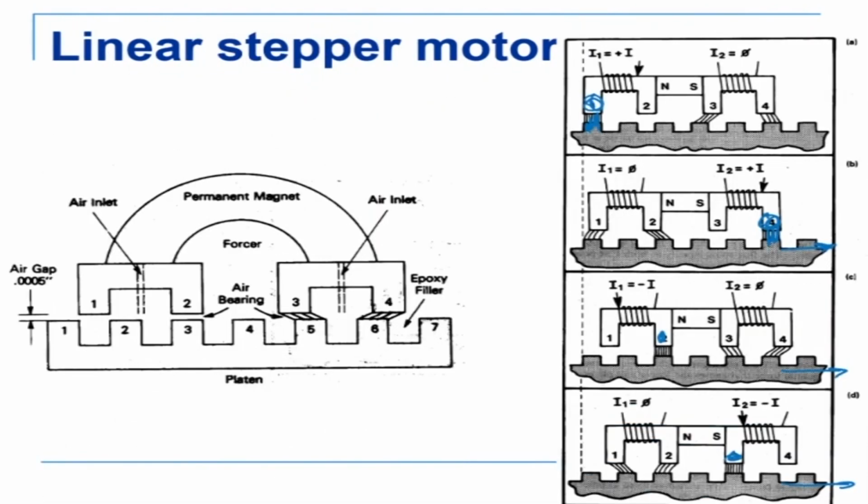We can also have linear stepper motors. So the working principle is exactly the same. We actuate these coils. I actuate this one first. So what happens? This gets attracted. Then I actuate number 4, so 4 will get attracted this side. Then I'll actuate number 3, so this will get attracted this side. As a result you see that this one is moved in this direction, right? So by sequentially activating these coils, we can make the rotor, well, it's not a rotor, it's a linear device, translate in that direction. These are called linear stepper motors.